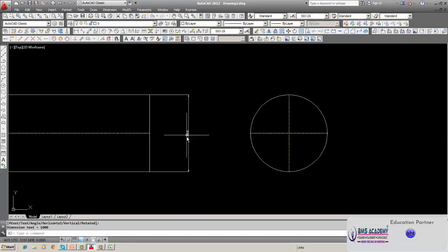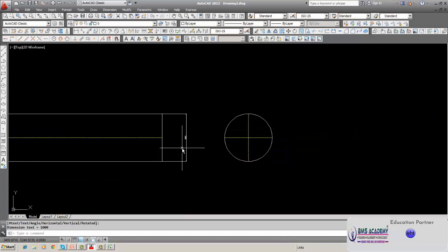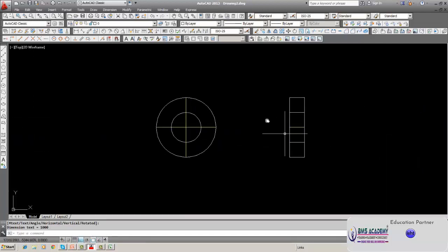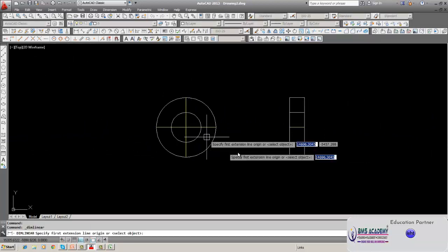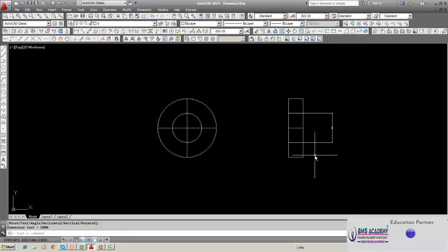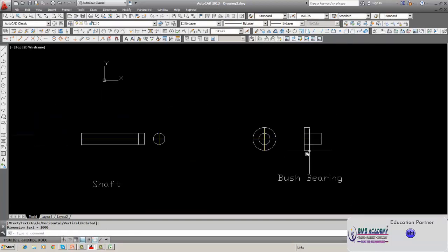I think you can see this now. This is 1000 diameter, the shaft OD. Similarly, the design size, this is also 1000 diameter. It has to run inside. Only you have to keep some clearance.